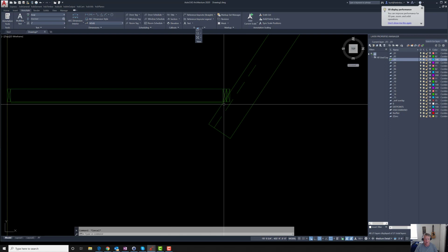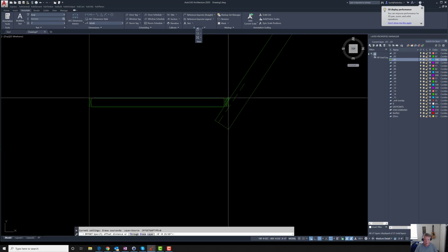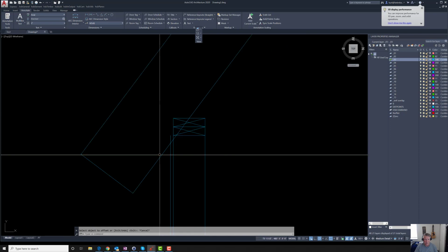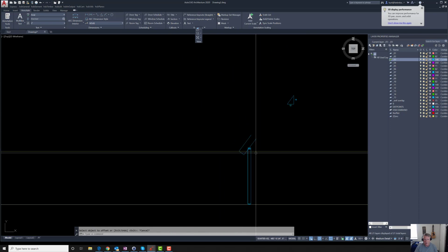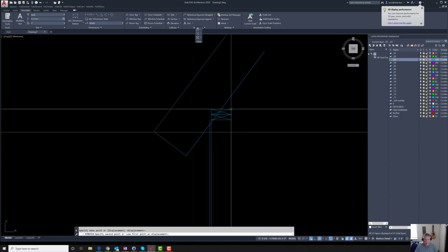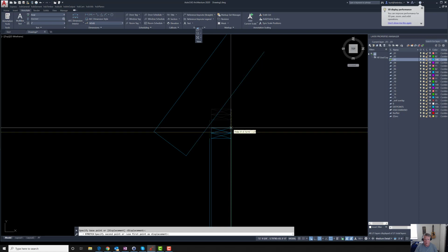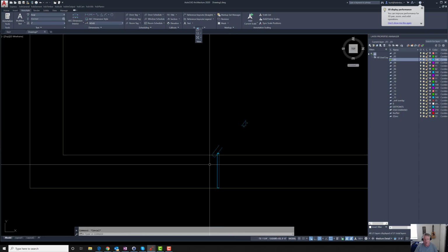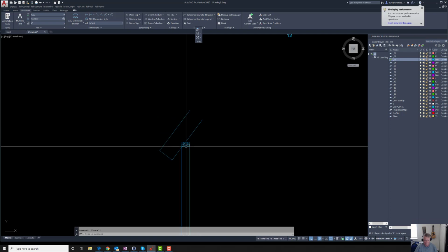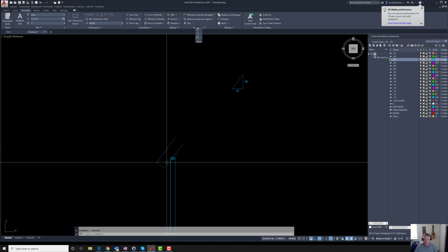But if I want to see if I can make that 8 foot wall work, I can do the exact same thing here. I'll offset this floor line to the top of the wall, compare that around to the other side, and see what I get. And it is not going to work very nicely for me, because if I want to use that wall height, I would have to have my wall down here for consistent fascias. So we're not going to probably be able to use a consistent wall height on this, so I'll just get rid of it and we'll use my half bearing solution for the 16 and 12 rafter.